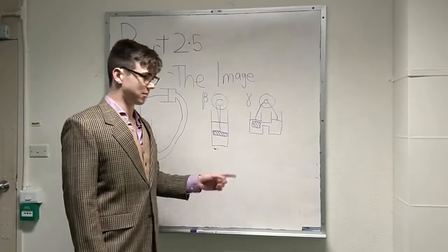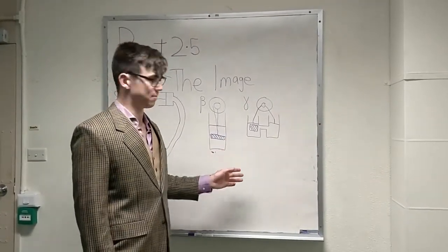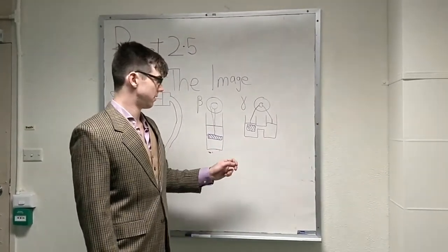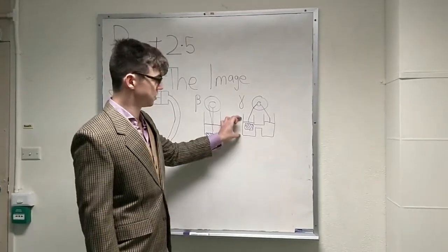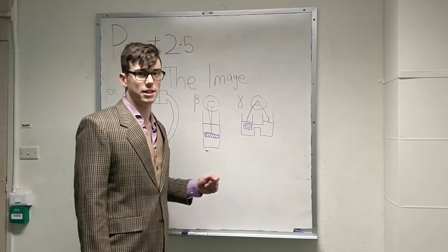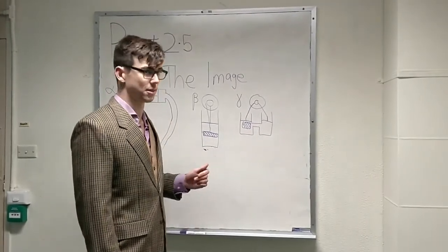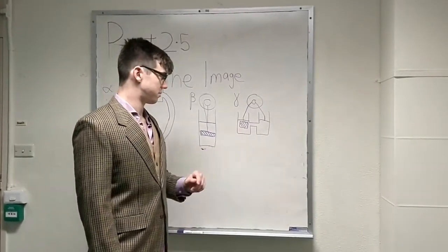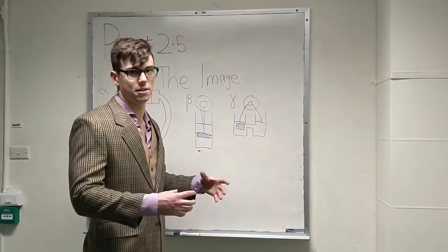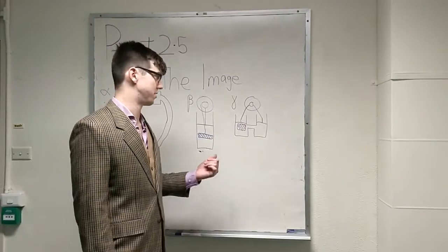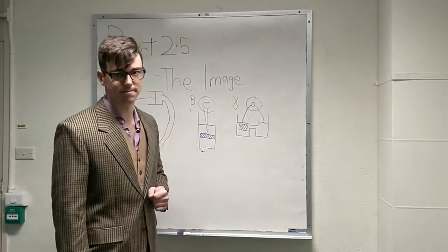Gamma type is similar to the beta type, however it tends to be more efficient as it separates the hot and the cold. Also, there is a displacer in the hot chamber of the gamma type, which is usually much larger than the cold, but drawn here at the same size to make it a little bit clearer. This displacement acts to help funnel the hot air into the cold chamber to increase the amount of compression and expansion this engine can have, increasing its efficiency.